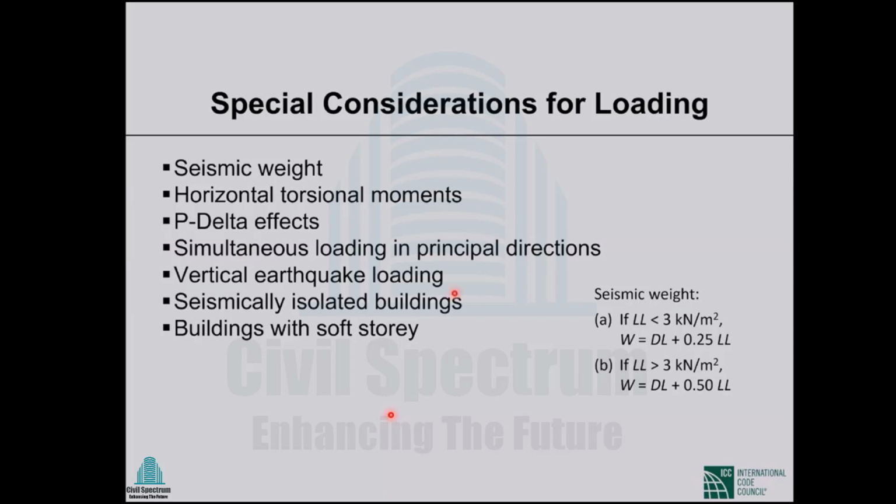The other considerations that are important for loading is seismic weight. In the previous version of the code, permanent dead load was the seismic weight. In the case of storage or warehouses, we would consider some portion of live load and add that with dead load as seismic weight. But this time we have to consider some part of live load as seismic weight.